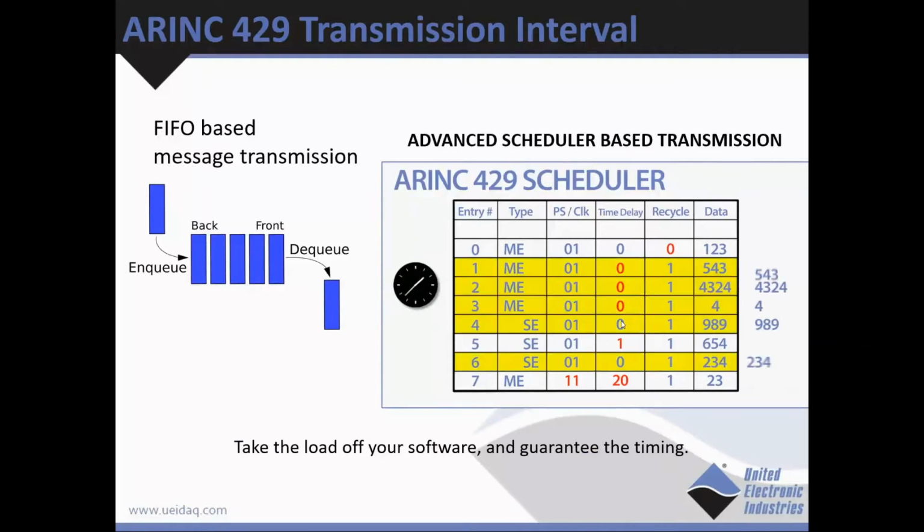Options for these can include master and slave entries, so one or more slave messages are sent only when the master message is sent. Messages can be transmitted at many different frequencies on a periodic basis. A message can be sent as a reaction to another message being transmitted. The second message can be delayed by a variable number of clock ticks. There can also be a notification to the application when a particular command was sent or received.